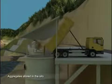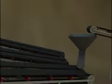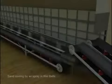Dumper trucks travel via an approach road to the aggregate silos and dump the crushed aggregates in the respective silos. A conveyor carries aggregates from the silos, one size of aggregates at a time, to the rotary feeder. The rotary feeder mechanism directs the aggregates flow to the respective conveyors and subsequently to the hoppers in the wet belt system. Hereon, all the facilities are covered and insulated to avoid heat loss.